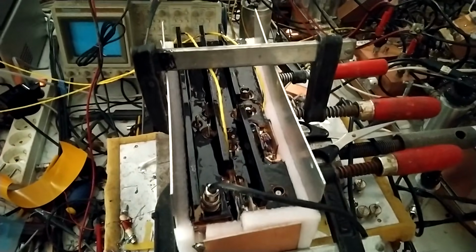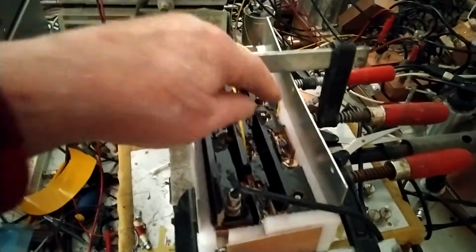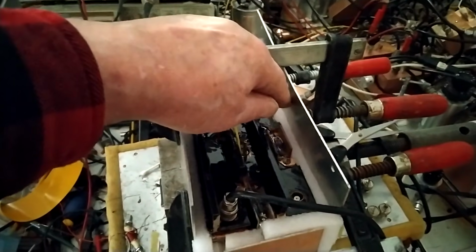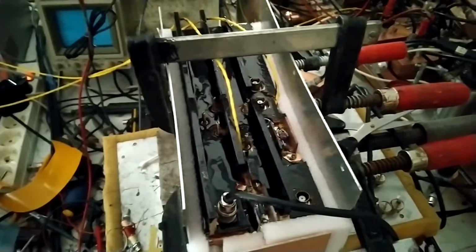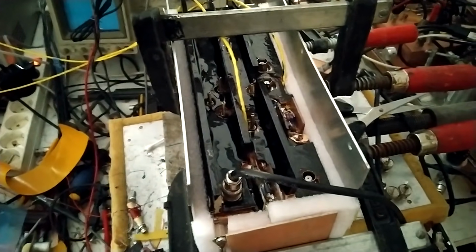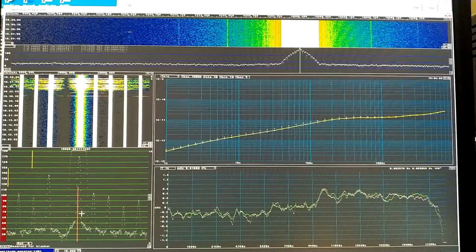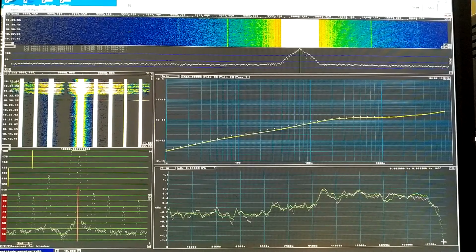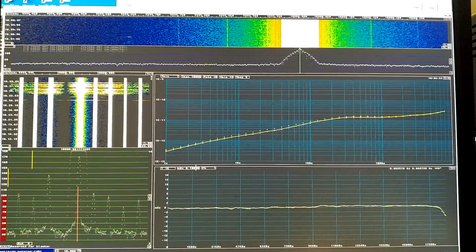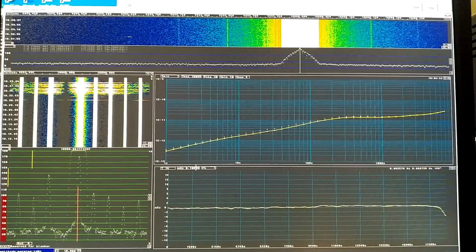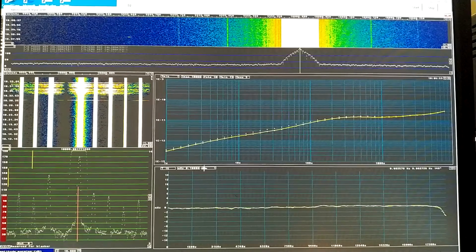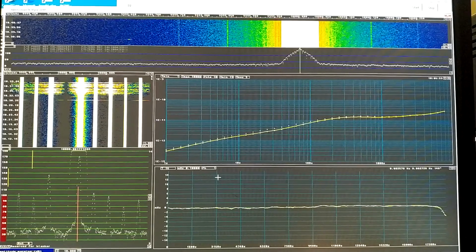The foam plastic had come loose. There was a 5 mm air gap between the box and the foam on this side. Now I hope this will be stable. The change in cooling has a profound effect on the frequency. You can see the signal goes here and out of scale. I have compressed the frequency scale by a factor of 10, and I see that the frequency change is about 4 millihertz. I will wait for this to stabilize before I start measurement.